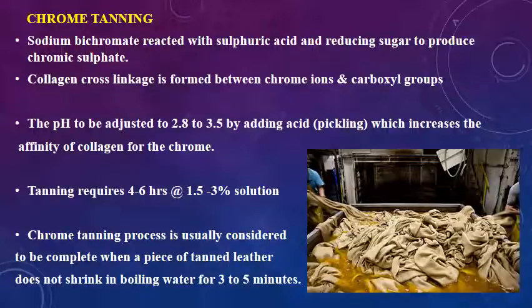Chrome tanning process is usually considered to be complete when a piece of tanned leather does not shrink in boiling water for 3 to 5 minutes. So if we keep a piece after this process over the boiling water, it will not shrink. That means the tanning is perfect.